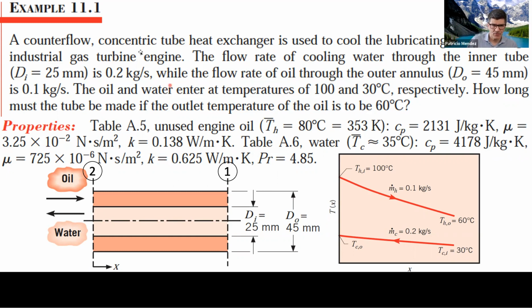So the counterflow concentric tube heat exchanger is cooling down lubricating oil. It gives you the rate of cooling water, right? Which is related to the pumps and the pressure losses. I will not deal with pressure losses in this class because we have our hands full with heat transfer. Pressure losses are something that relates to fluid mechanics. Now, when you have your design class, you'll have to deal with both the heat transfer and the pressure losses. You can design an amazing heat transfer, but if there is no pump that can pump through it, then there is no point.